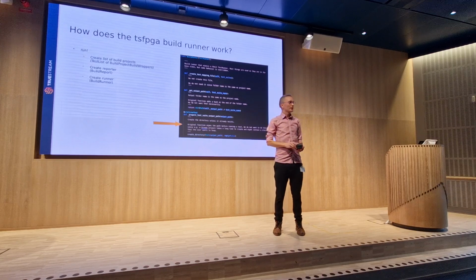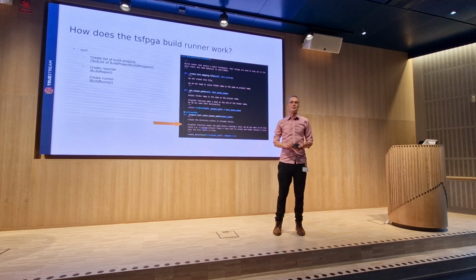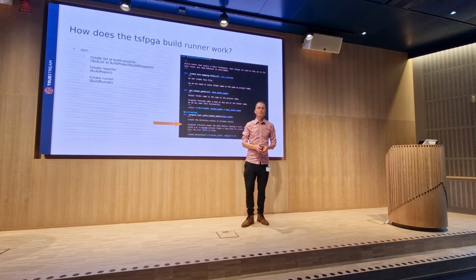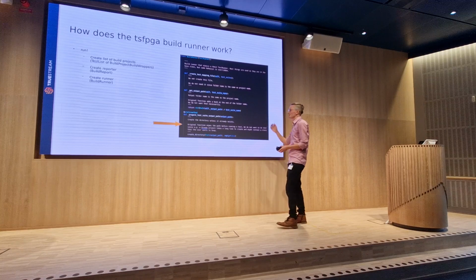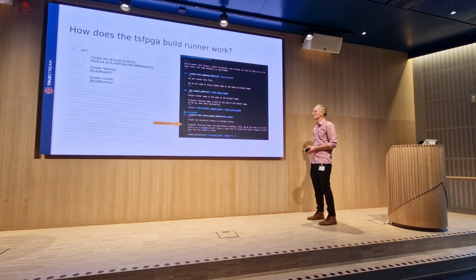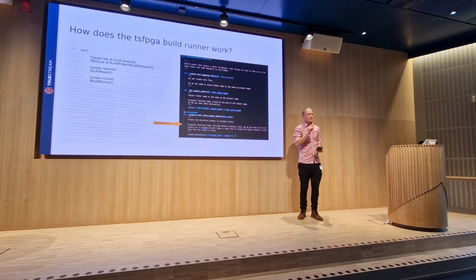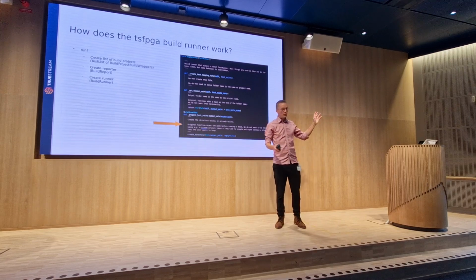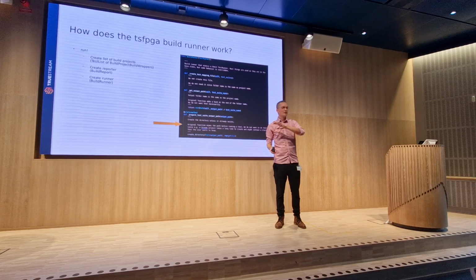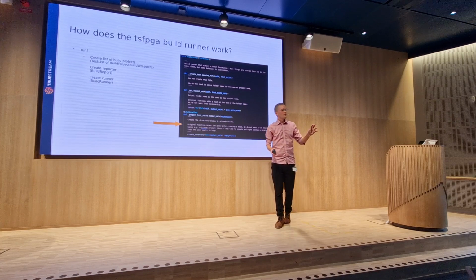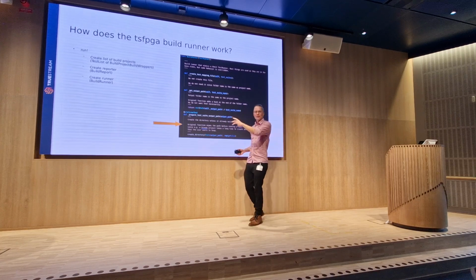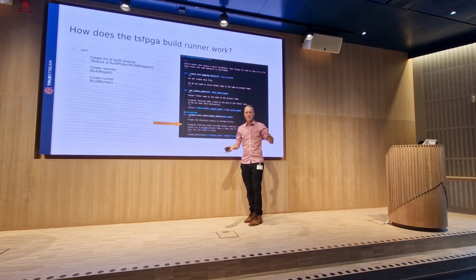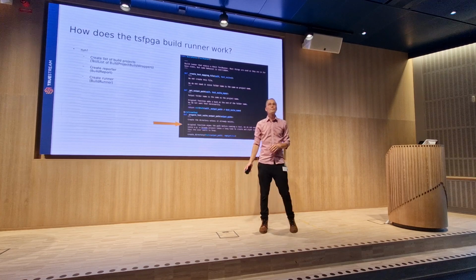We then create a runner, and instead of a test runner, it's a build runner, which is based upon the VUnit test runner. Again, three methods to overload. The primary difference being that VUnit will always purge the output path before beginning a simulation. But when you have a build project in there, you don't really want to wipe it every single time because, you know, it may take some time to set it up.